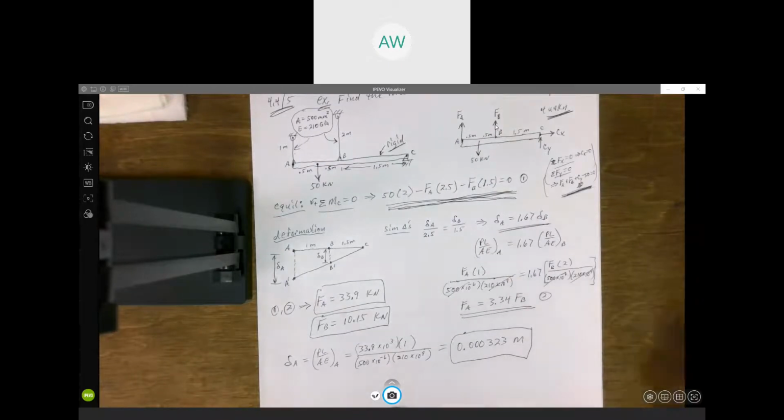And more often than not, when you get a completely unreasonable answer like that, it has to do with these units. Like, if instead of giga being 10 to the ninth, you use 10 to the sixth, you just multiply this by 1,000. Or if you just do 210, you just went 9 decimal places. I've had it in the past. Somebody told me the displacement was so big it was larger than the distance between the Earth and the Sun.